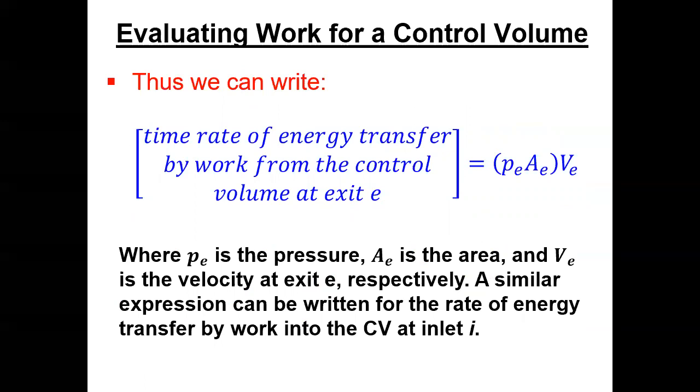So if you think about it, again, you can look at units. Pressure, say, pounds force per inch squared, area inch squared. So then that's a force, and then that's a velocity. So pound force foot per second.